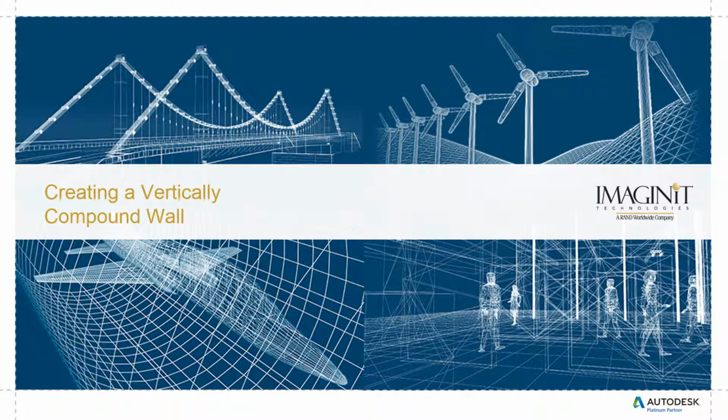We make a new material called studs with insulation, and then we take 20% out or 10% out depending on what stuff we're using for insulation. When you say 20% for the takeoffs? Yeah. So if you just want to show it, then you can say stud with insulation when you tag it. But if you're actually trying to get material takeoffs or calculations, what he's recommending is a percentage taken out when you do that, because you're doing your calculations on it. Because you also can't tag the insulation.